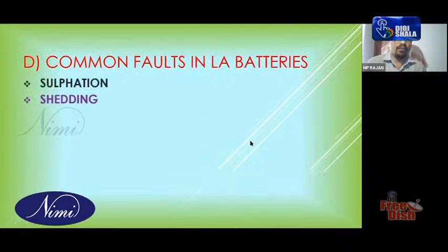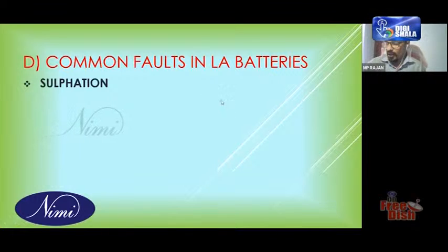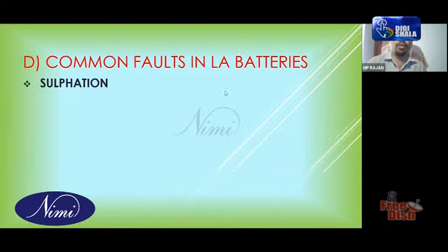So, common faults. We should know what the common faults are when we treat a solar power system. We say there is totally no maintenance, because as far as the panel is concerned, there is no maintenance. But when you are using the battery, it requires maintenance. We should check the condition of the battery. Sometimes the battery has to be replaced also if it is damaged.